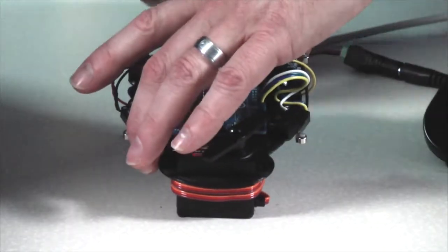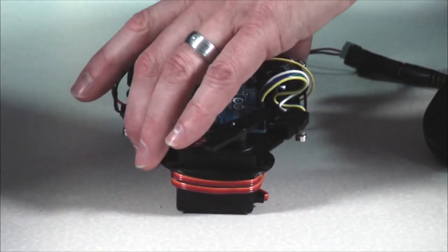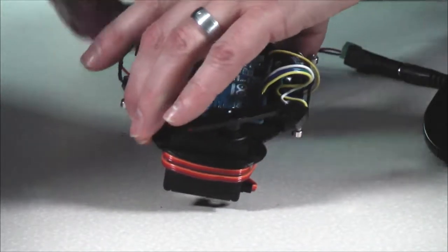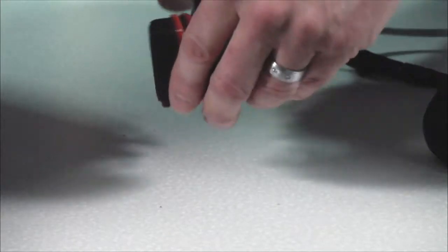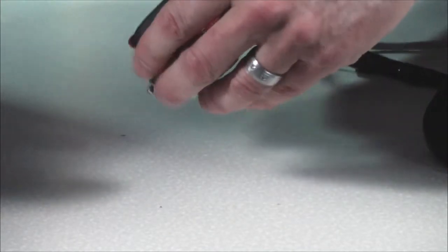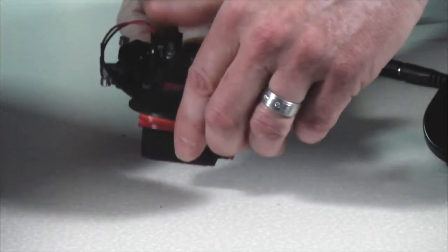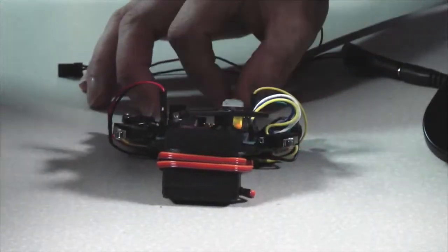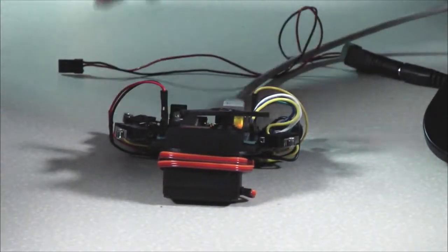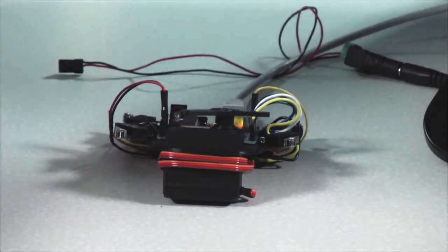So I am going to plug in the board to my PC so that we can upload that program. It looks like we're running off of the power supply off the USB. I wouldn't say that's a best practice for a servo, but we can get away with it here because we just have one and we're not going to pull too much power.